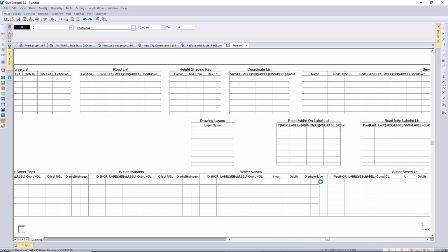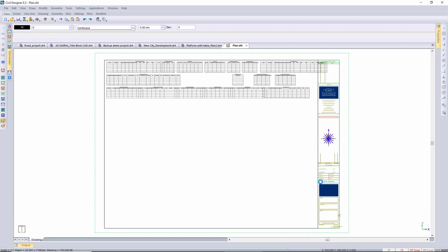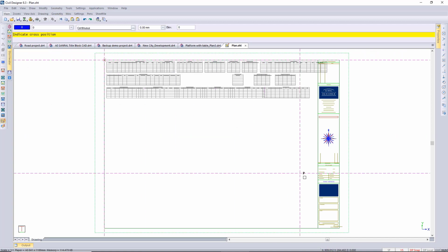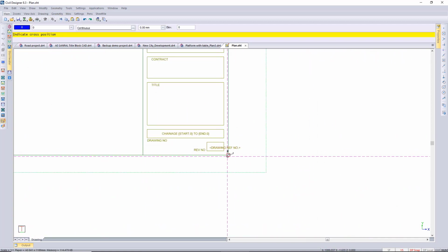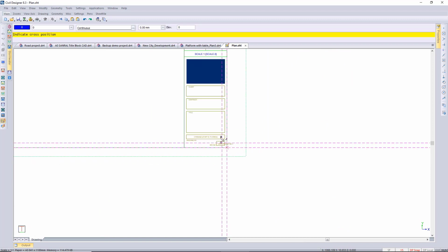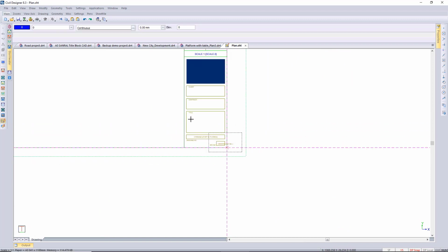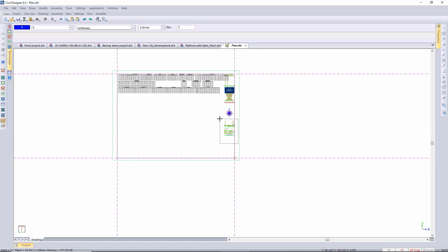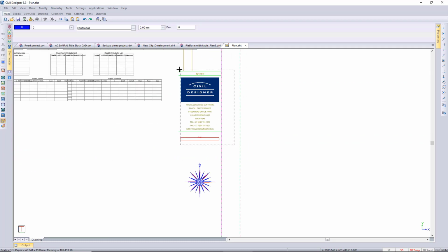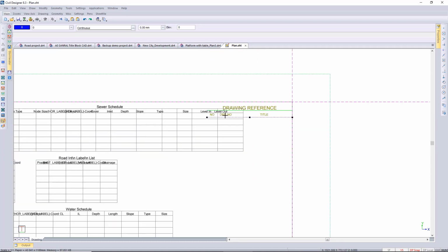So what I'm planning on doing here is putting in a custom title block. So we're going to be removing the existing title block. I'm just putting in some geometry just in case my global region gets disturbed while I'm deleting. So I'm just going to drag selection windows, crossing selection windows just to delete all the existing CAD.